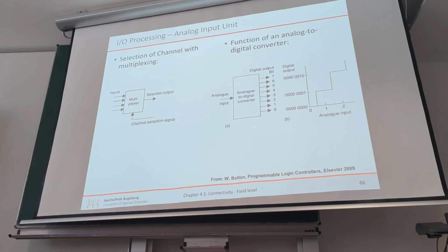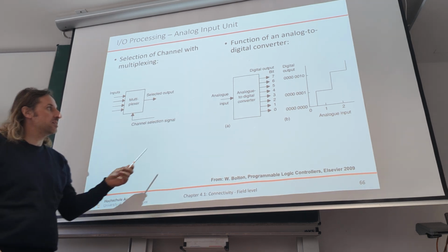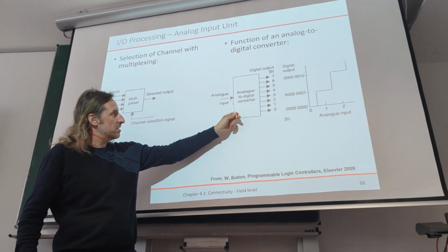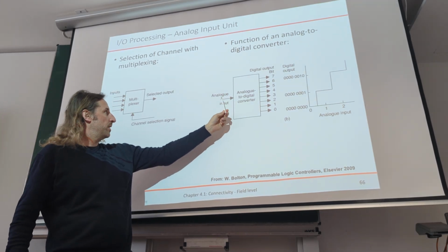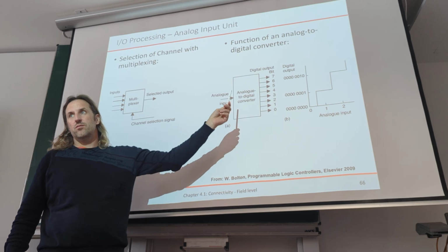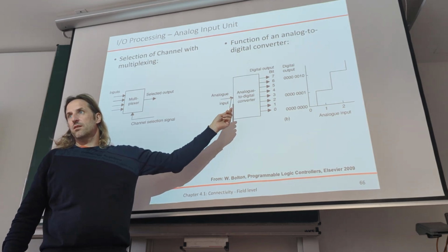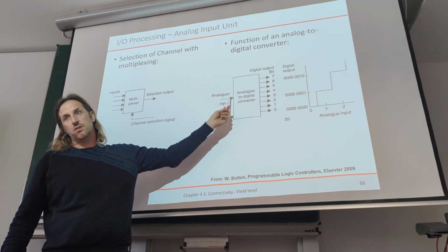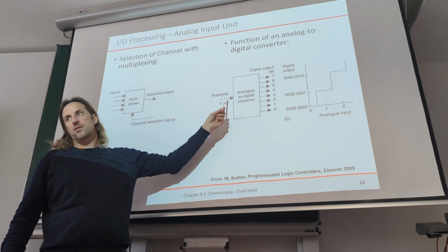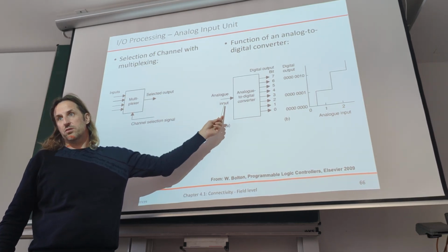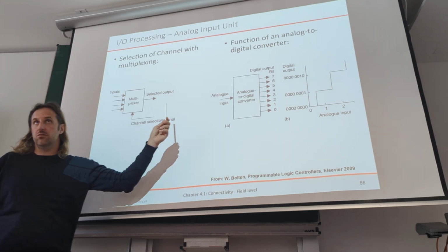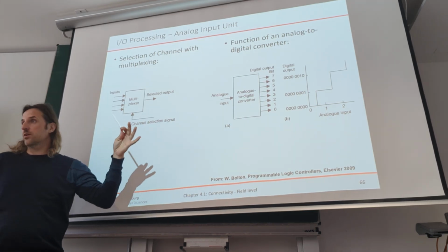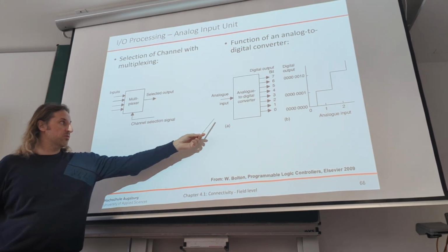Because there you want to measure accurately but fast signals. And because these signal converters are kind of expensive, by now they all have conversion frequencies of megahertz or even more. And that is far more than we usually need in the automation world, because here we're talking about kilohertz cycles, so that's far more than we need.